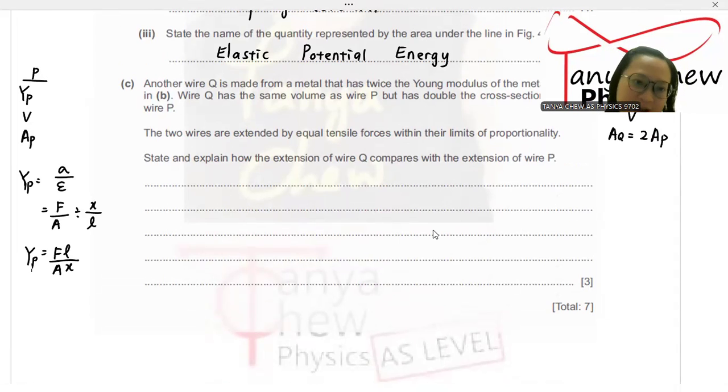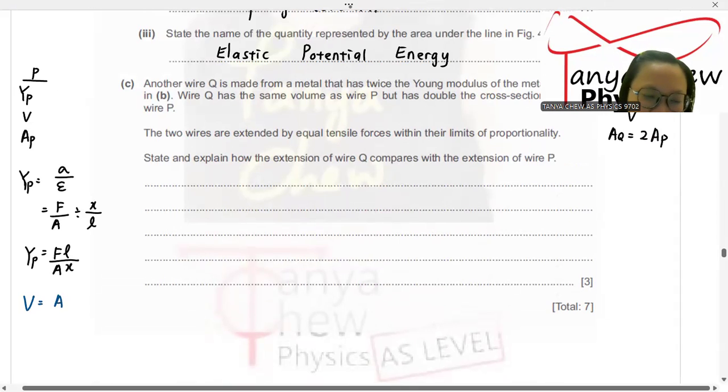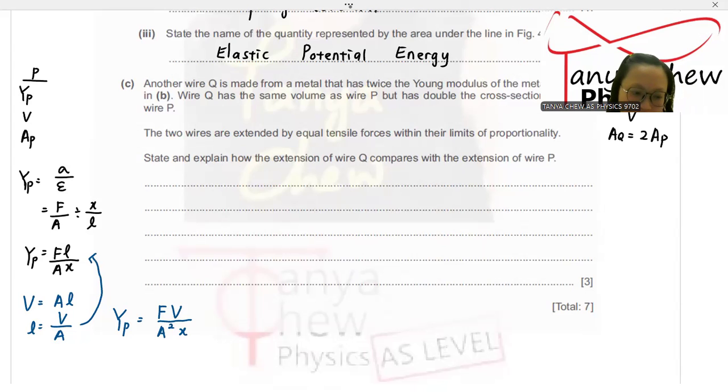So I'm going to replace the length. Volume is being given, right? The question did mention that the volume is the same. Now I'm going to do it here. Volume is equal to cross-sectional area multiplied by length. Therefore, length is equal to volume over area. Sub into this equation. Young modulus of P is equal to force times volume over area, right? Area times this area, you will get area square multiplies by extension, right? That is extension of P.